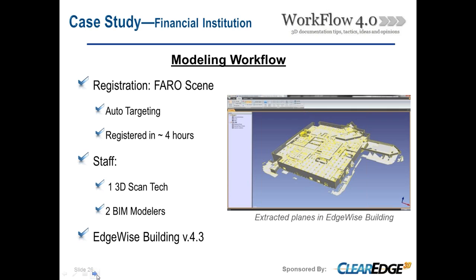So back at our office, we started the process of completing the scan registration. We use FARO Scene software for this process. For those of you who haven't used it, it's got a pretty robust auto-targeting feature which goes through the scan data and acquires the sphere targets automatically. That really shortens the registration process. So for this project, we were able to register everything in just under 4 hours.